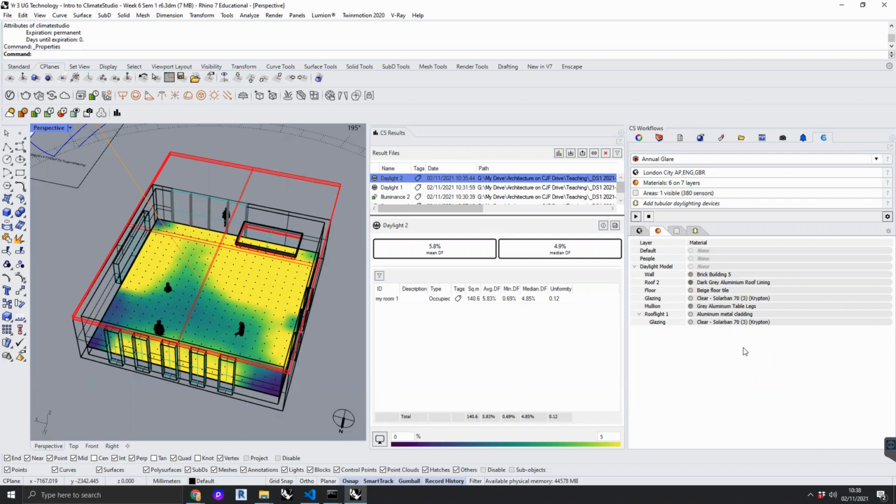If you maximize your daylight factor to get lots of lovely natural light into your building, but you then also say that you want people to learn in your building, then both the glare and the heat are potentially going to be a problem. Does that make sense? You've got these things to play with, but none of this software is going to give you the answer. You have to work out what you're willing to live with and what compromises you need to make somewhere that is going to be nice and is going to actually match the human aspects of your design.